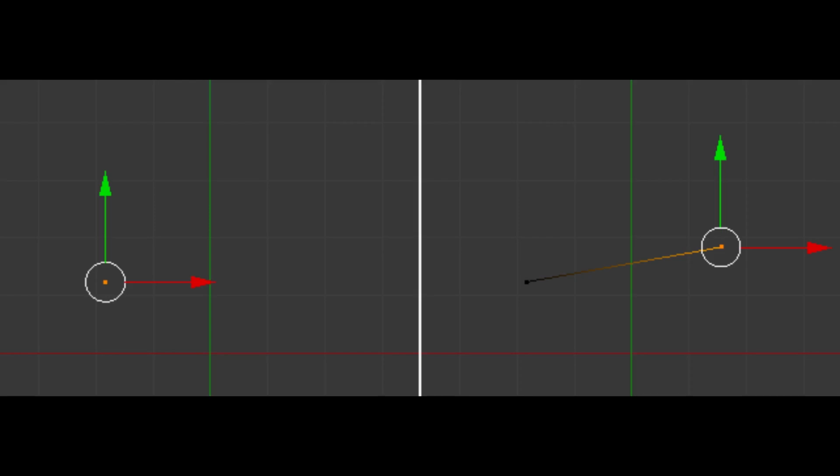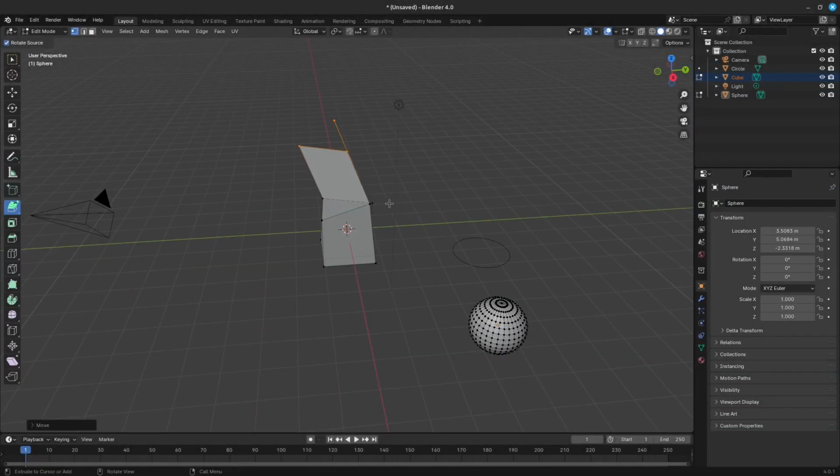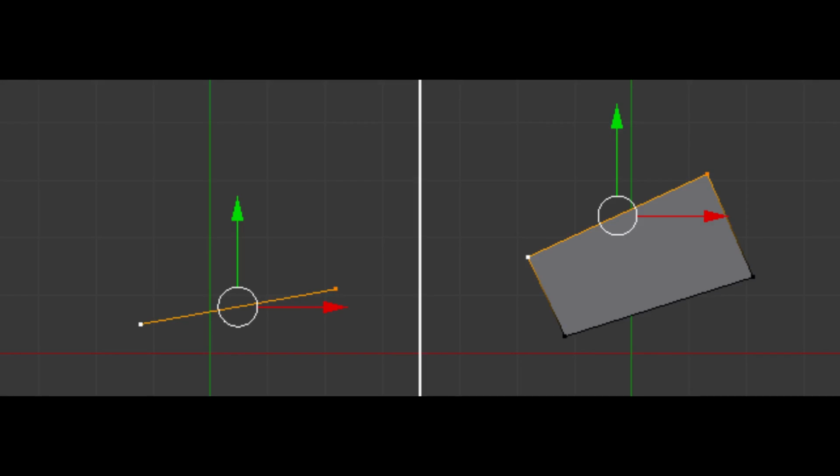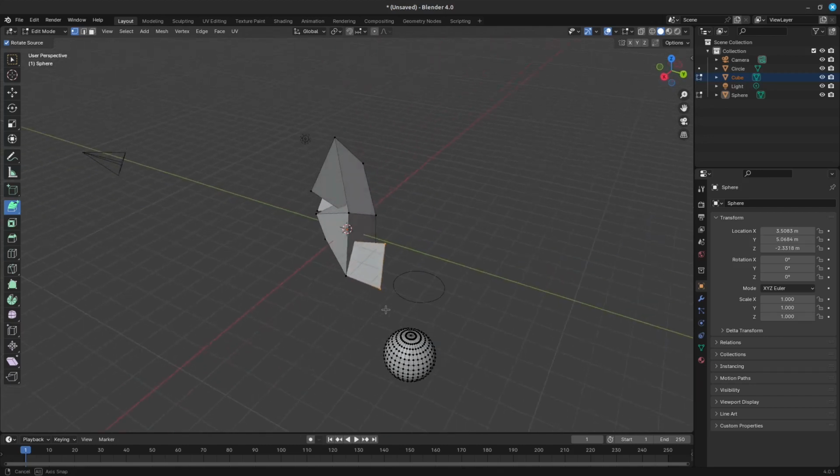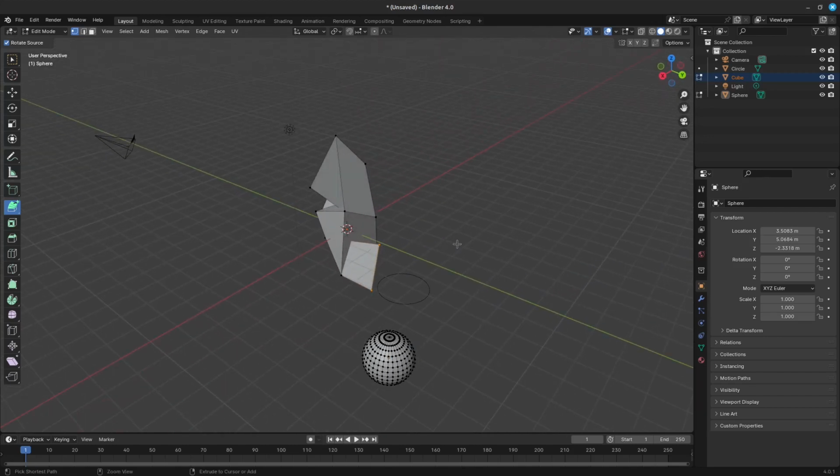To create interconnected vertices, you can add a vertex and continuously make subsequent Control plus the right mouse button operations with the last vertex selected. This will link the last selected vertex with the vertex created at the mouse position with an edge. If you have two vertices selected and already connected with an edge, Control plus the right mouse button click will create a planar face, also known as a quad. Blender will follow your mouse cursor and will use the planar view from your viewport to create those quads.